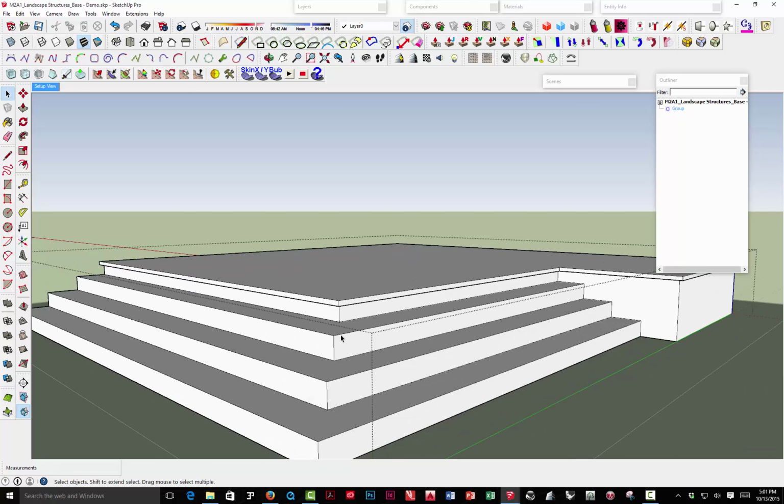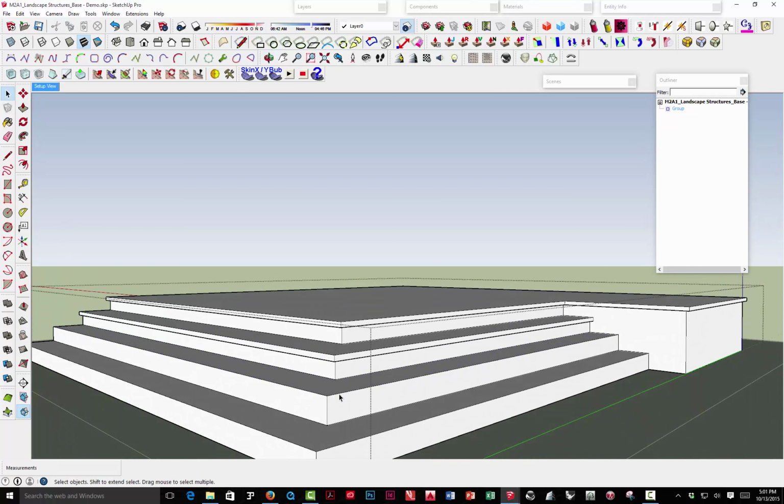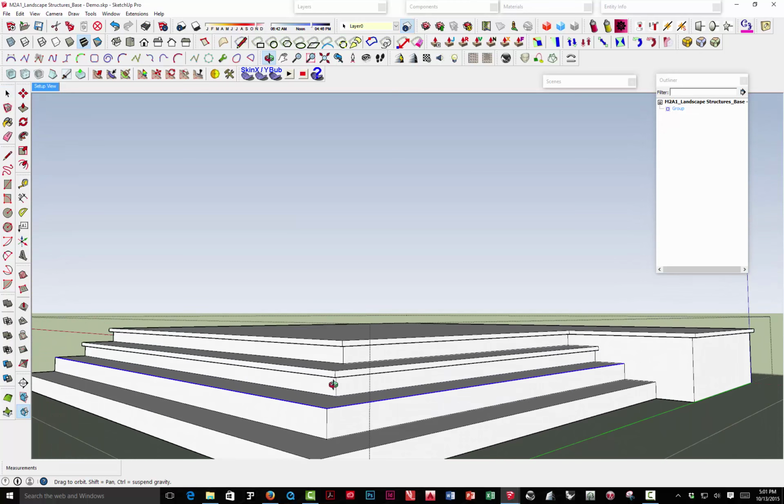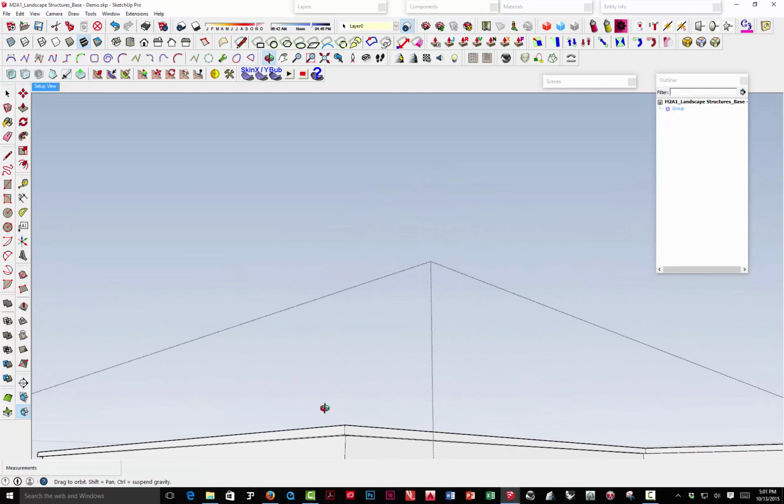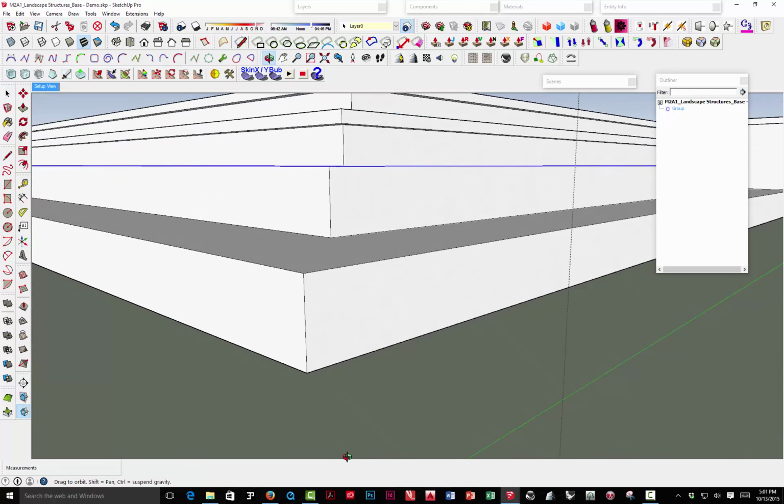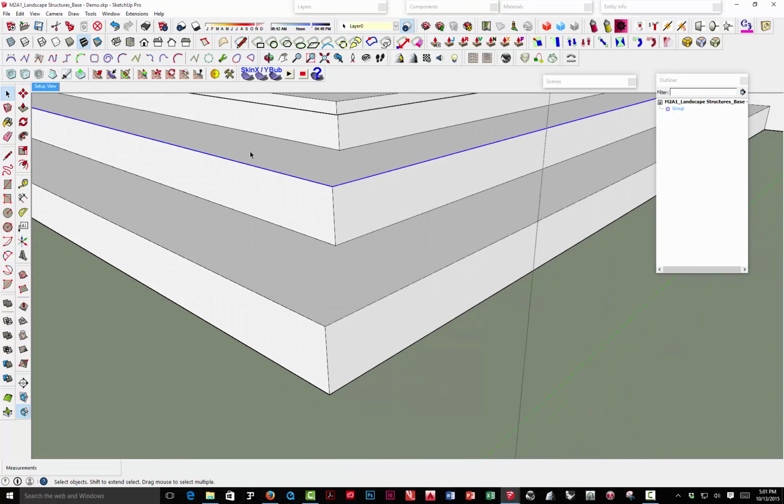So now let's do the same thing on the rest of the steps. In this case, I'll just grab these two, control move, 1.5 inches. And you also notice, okay, double click, space bar to get select. One thing that you'll notice that I'm doing here, so to get my view straightened out, is when I go to move this, move tool, I'm not clicking randomly out here. I'm going to click right on this corner, hit the control key, and pull it down because I know I have to move it perfectly vertical.